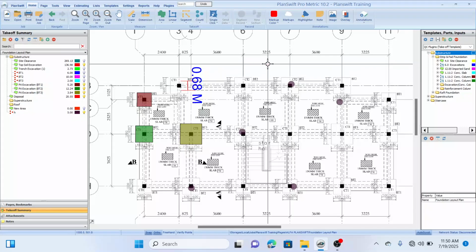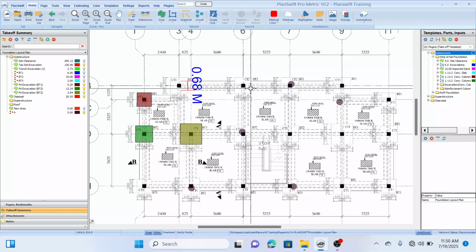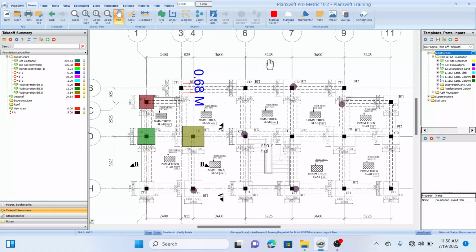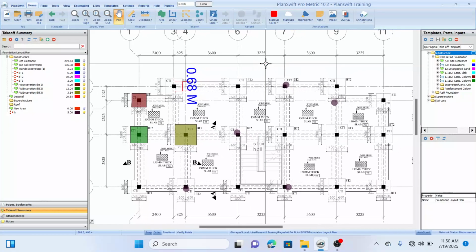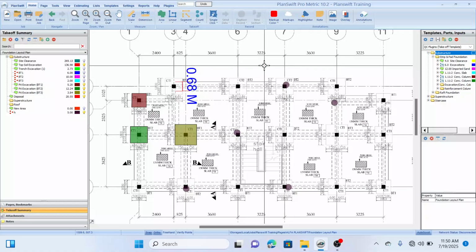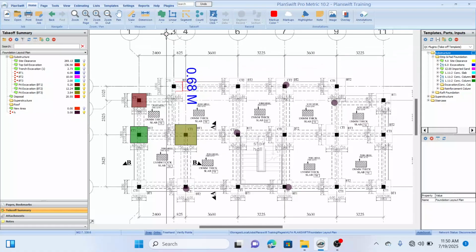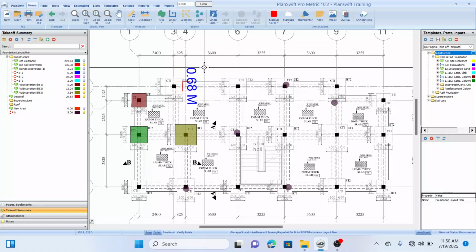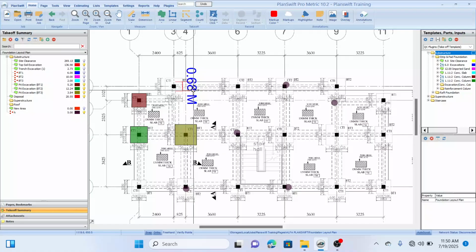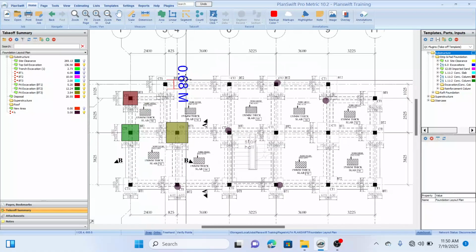While if I measure my pad foundation, it will automatically measure concrete in column base, and I'll be able to measure reinforcement in column base too, alongside the formwork. So using the plugin for measurement is way faster than using the software tools. So let's measure.